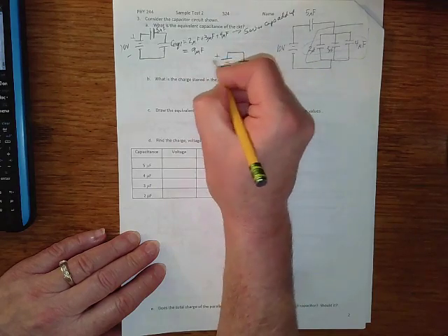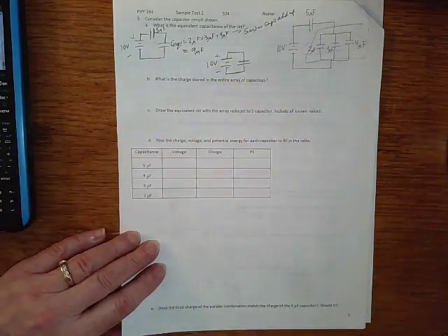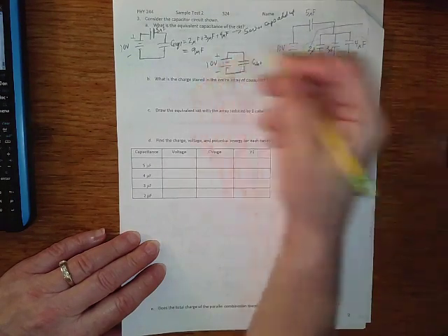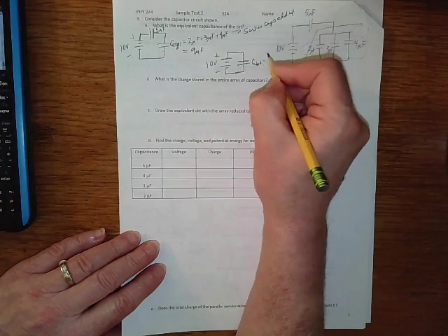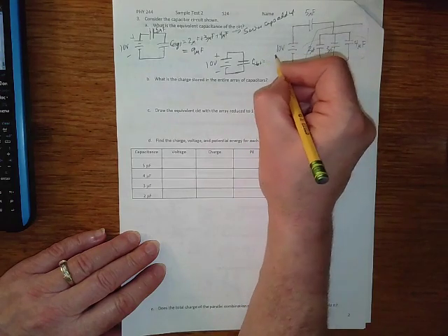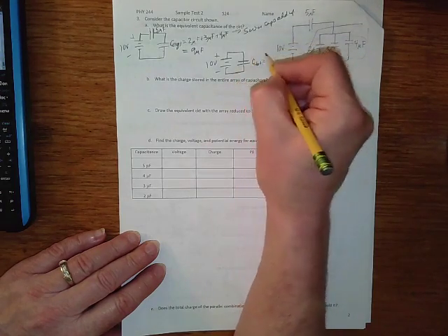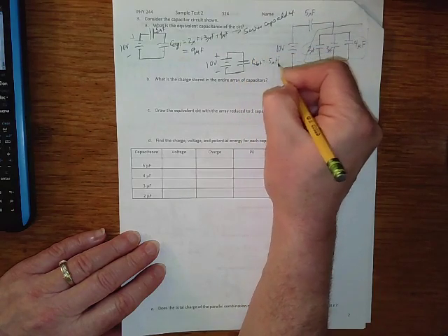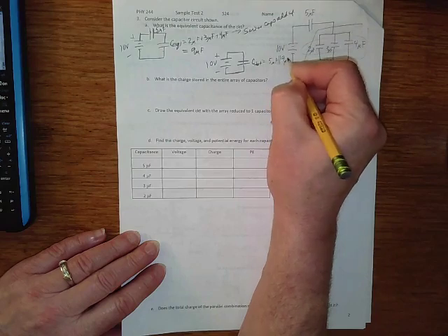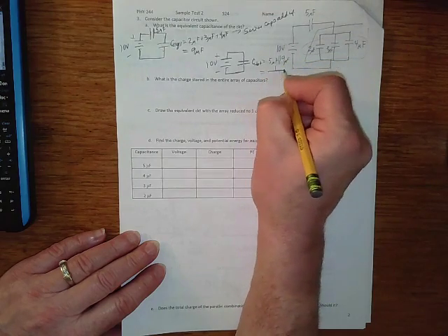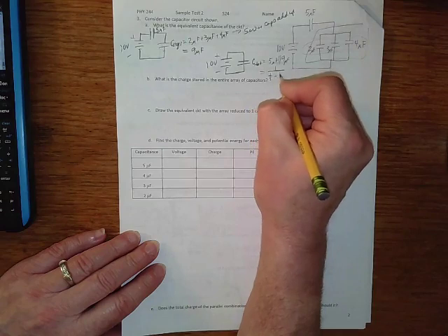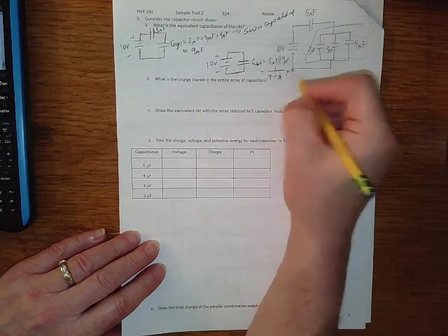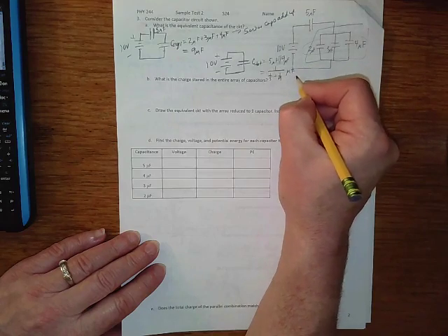We still have the same 10 volt source. It doesn't know anything's happening here. But now we're going to have C, let's just call this one C total, just to call it something different. And it's going to be for C total, 5 microfarads in series with 9 microfarads, which is going to be the 1 over 1 over stuff. So 1 over 5 plus 1 over 9. If we leave everything in microfarads, we're okay to do this as 1 over 5, 1 over 9, kind of whole number things.